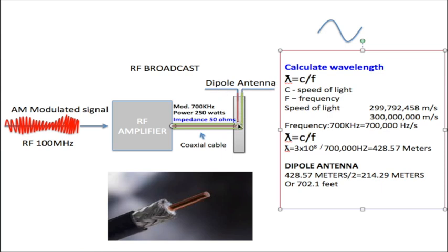Nothing is being reflected back. And the impedance of your antenna should be 50 ohms at this point. If you have 1 to 1.5, it means a little bit of the signal is being reflected back. It's only at 1:1 that your impedance of your antenna is equal to 50 ohms. Okay?